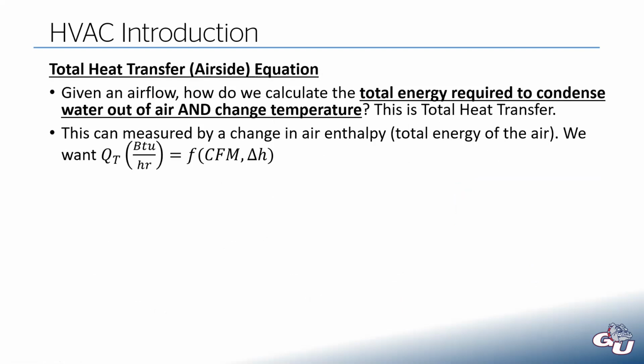That's our total energy of that air. So we want that Q total to be a function of airflow and our change in enthalpy, because that enthalpy factor will contain the delta for both the temperature and the water content, because that's the total enthalpy of the air.